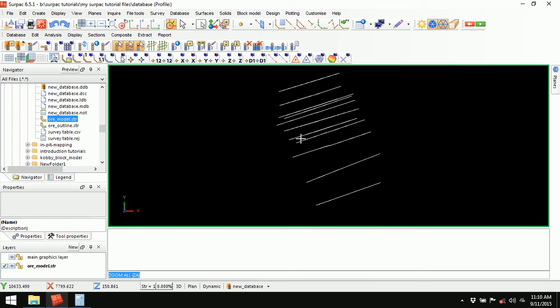A string or segment can take two directions, either clockwise or anti-clockwise, but in geological modeling, your strings should be clockwise. The clockwise nature of the segment or string will aid in validating the solid, taking away the hassle of re-editing and other validation problems. In other words, it helps to create very simple and well-formed three-dimensional models.